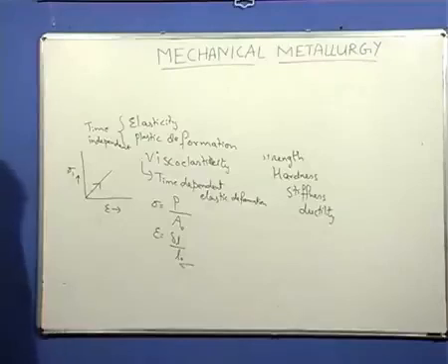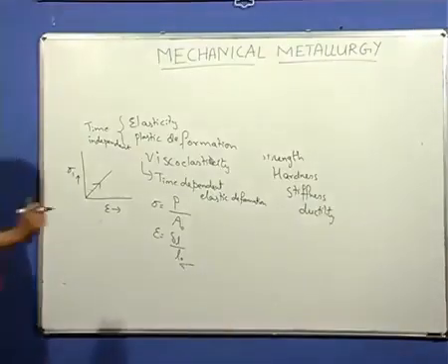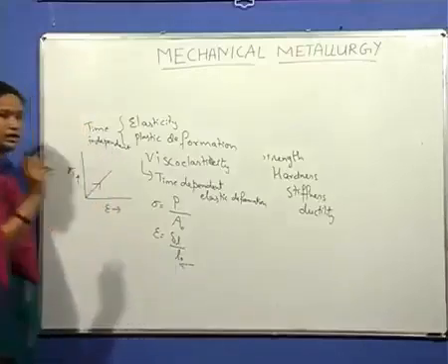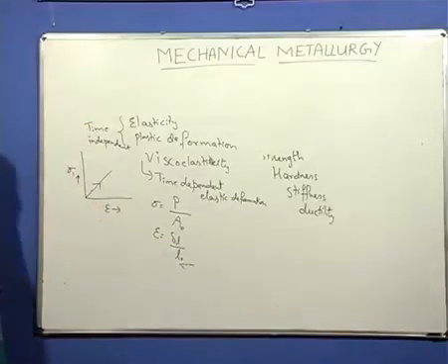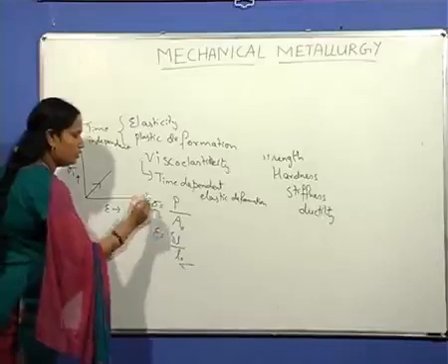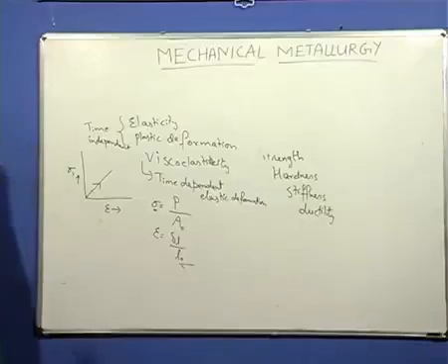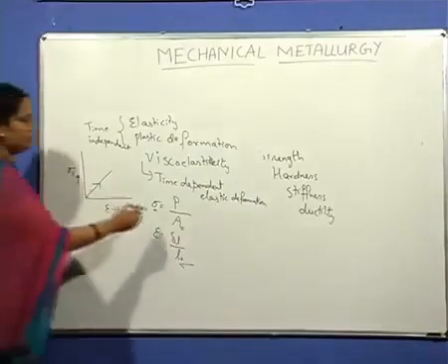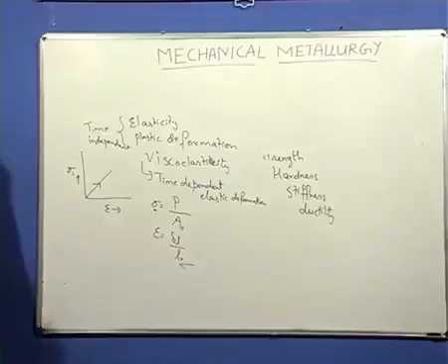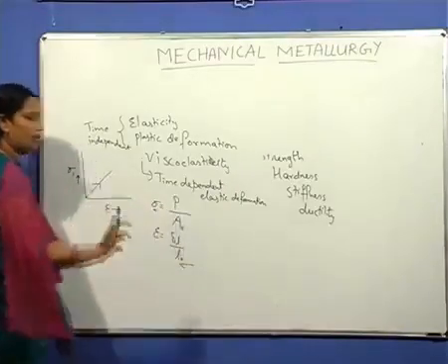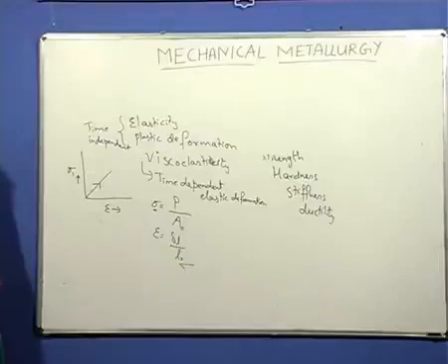If it is tensile, the material undergoes an increase in length. If the force or the load is compressive, it undergoes a decrease in length. So the change in length over the initial length is the strain. And the stress is the average stress. The stress, what we normally talk about, is the load over the cross-sectional area over which the load occurs. It is the average stress, because all materials are not homogeneous.